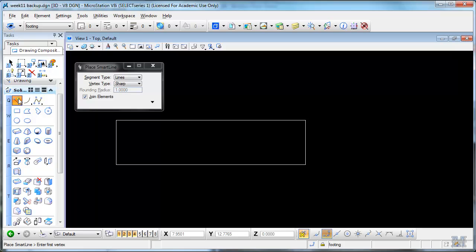I think I'm going to do that in 2D and then thicken it. So starting from this back corner of the footing, I'll tentative, which is the middle mouse button or both at the same time, O key, up a meter, left click, space bar to polar AccuDraw, because I'm going to draw them at an angle, which is the way you usually see them. Go back 12 meters at an angle of 25 degrees.